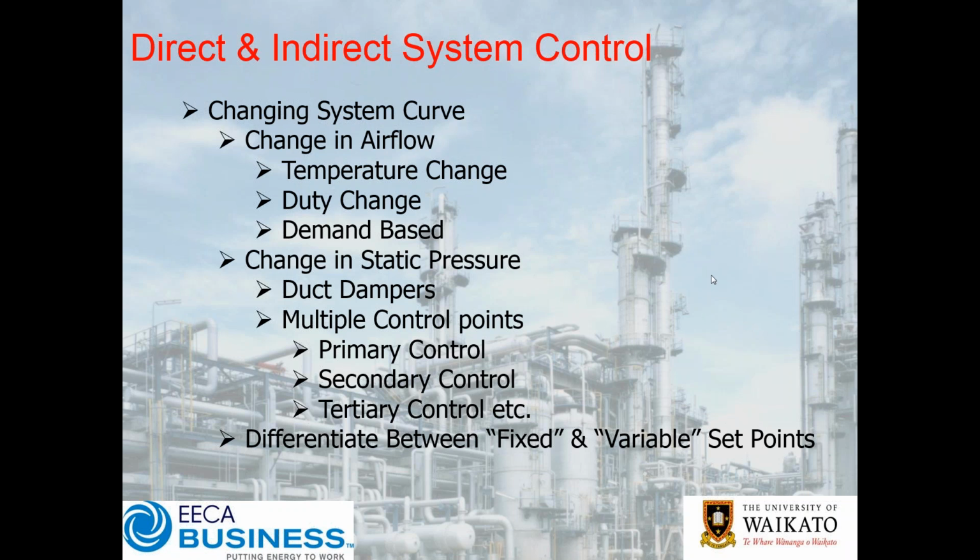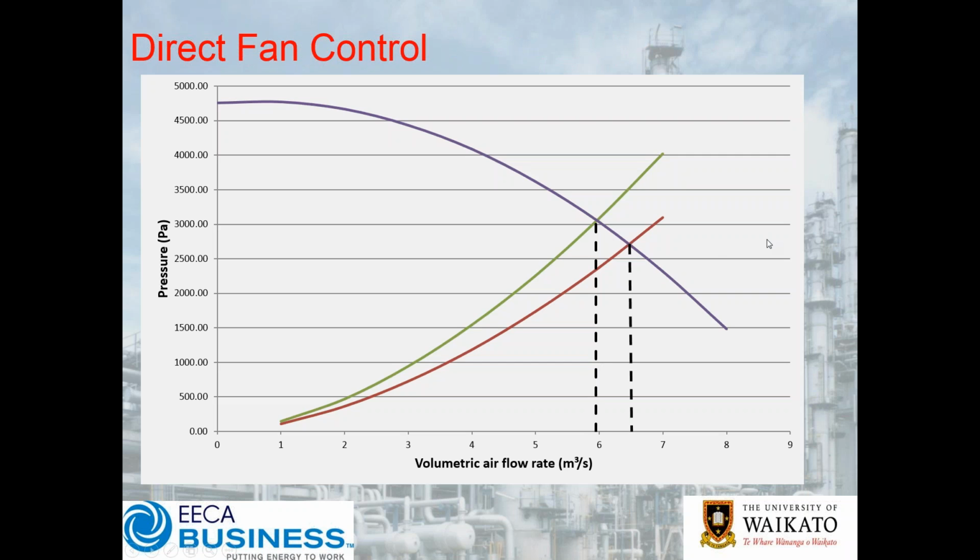And what I want to reiterate right at this point in time is that it's also very important to remember that every time you put a damper valve into a flow stream and you're damping the flow to control it, you are disturbing the flow and potentially impacting downstream where that flow's going, be it a drying bed, a fluidized bed, some sort of reactor vessel. You are disturbing the flow, and that may actually adversely impact the efficiency and performance of the system that it's feeding. Okay.